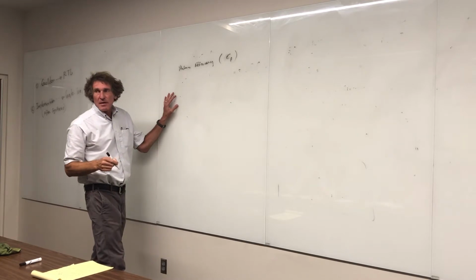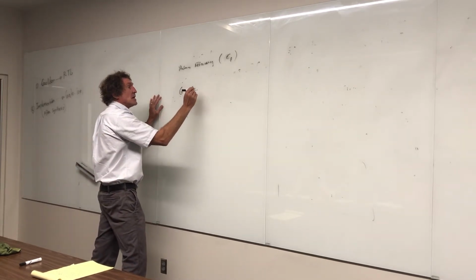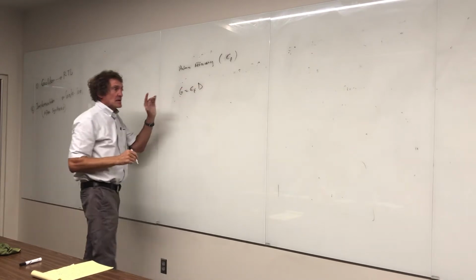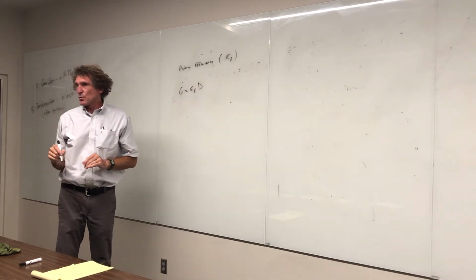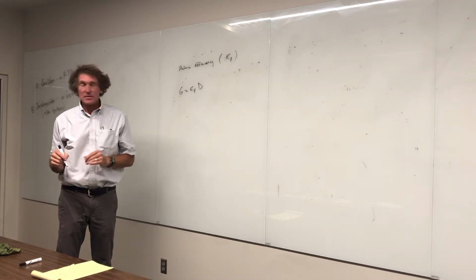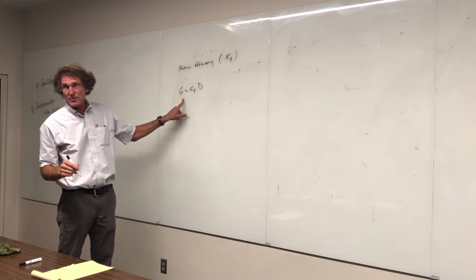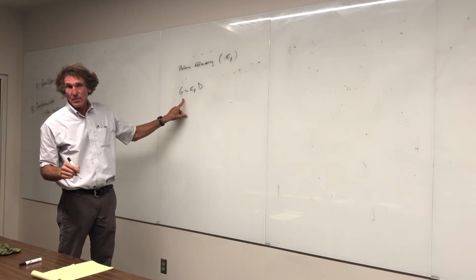It's small epsilon f, antenna efficiency. Remember, gain is equal to EF times directivity. Now, directivity has to do with the actual antenna's radiation characteristics only. It has nothing to do with any losses. Gain incorporates the losses. It's the true measure of how well an antenna is performing.